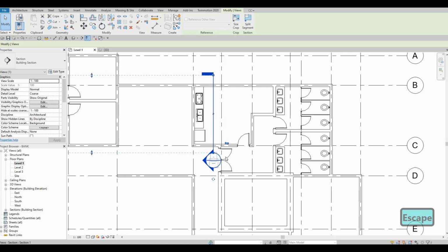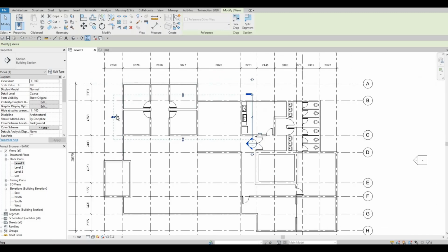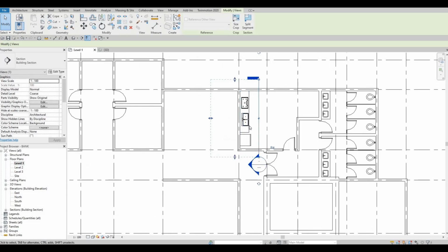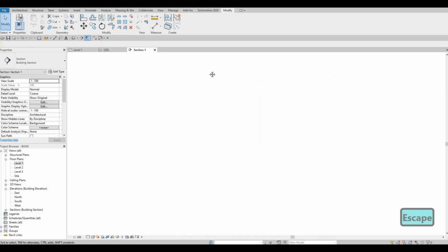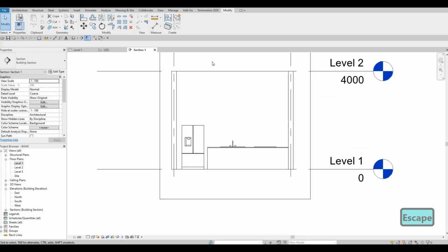If you add it from top to bottom, you could just flip it, so it's easy to flip with that arrow. And then here, the view range of this, I just want to see it from here up to here. So now you can click on this one so that it faces like this, and we have this wall at the back.